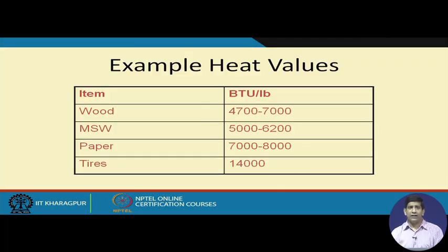In some pockets of India, maybe if you go to, say, South Extension in Delhi or some very posh area where people don't care about plastics or paper being sold from their houses, it may be possible. But since our plastics mostly get picked up by the kabadiwalas, and paper gets picked up by the kabadiwalas, we lose some of those. And then whatever is left from the secondary collection point, the rag pickers take it away. So if you look at the calorific value of the waste which is reaching the landfill or the dump sites today, it will be much less.